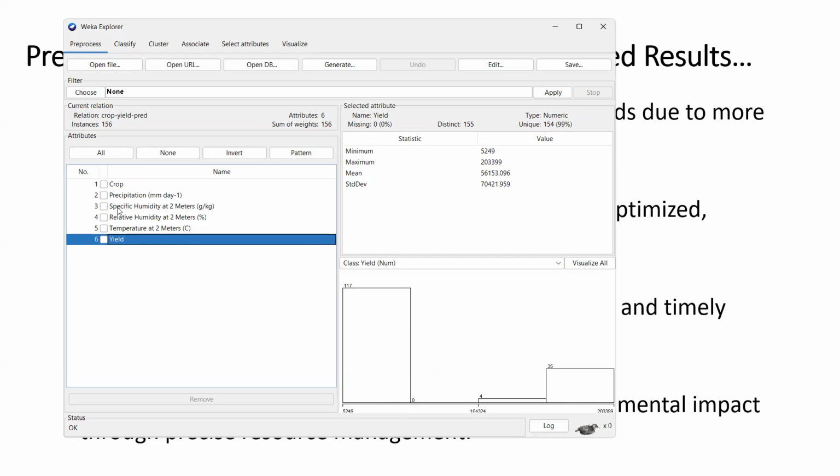And usually, it's good to let the target be on the rightmost part of your Excel file. When you are building your data, the rightmost part should contain the target. Of course, it can be any part, but you have to set it manually to indicate which one should be the target. If you forget, it means you'll be predicting wrong information. So I usually encourage people to make sure the rightmost part of your Excel file contains the target variable to be predicted. Now, let's look at it. Once we have loaded the file successfully, we go to classify.